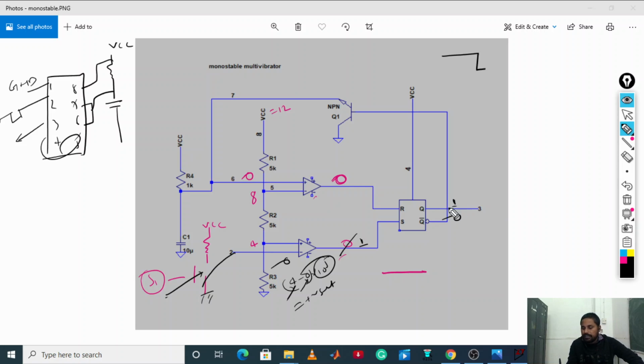Output is 1 and 0. Now your output is going to come back to 1. Now if you draw the output, this is the output you are going to get. Now when output is going to become 1, this will become inactive because this 0 is being applied over here. When this is inactive, it means there is no connection over here, because this transistor is not connected over here.